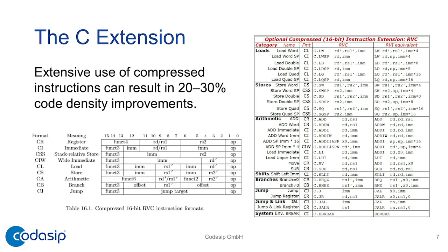If you look at the spec, we can find something like this. We have 8 basic encoding styles, and I copied and pasted the cheat sheet for the C extension, so you can see a list of basic C instructions plus their meaning in the full RVI equivalent.